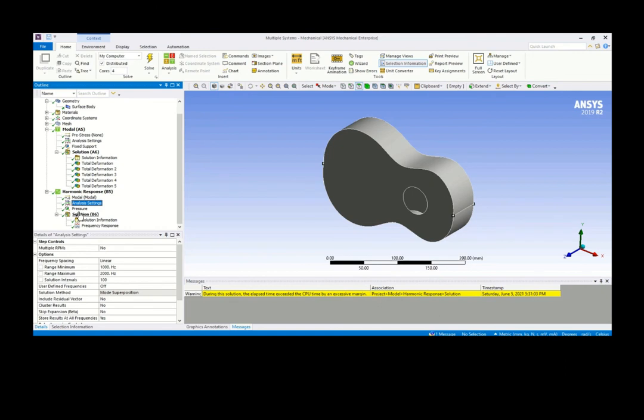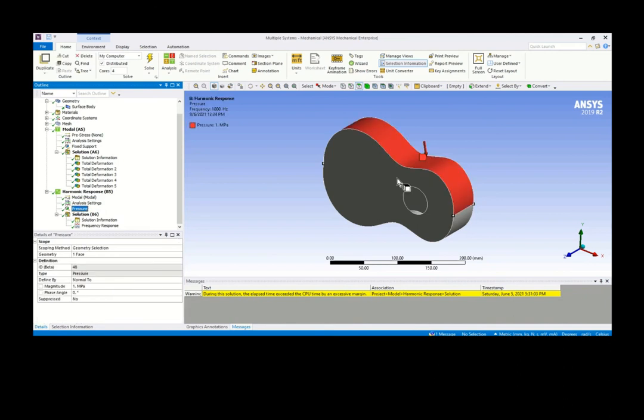Remember that under harmonic response, we want to calculate X. We have the natural frequency and mode shapes. We need to have the force. We need to put in the input of the force. So here the force is along this surface, 1 megapascal.